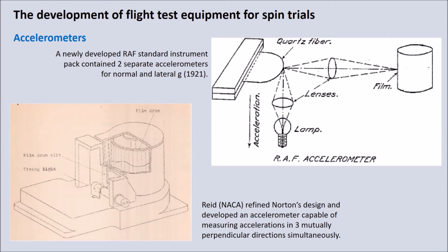So for the first time, we were able to get accelerations in three axes. The design had shutters on the individual lenses. They would open and close at different timing intervals, so that for the three traces on the time history, you got solid, dotted or dashed lines based on how quickly the lens opened and closed.